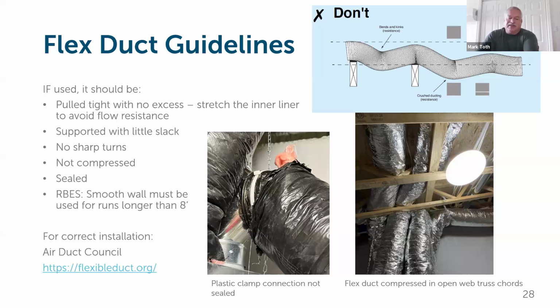So obviously here, I see this a lot, this picture right in the middle. Whether it's on an ERV, HRV, or heating and cooling systems, you see a lot of times they zip tie that inner tube, but they don't bring the insulation over, and they don't secure the insulation. That's definitely a problem. It leads to a very messy system. The one on the right, it's all good. It looks fine, but we have to be really careful.